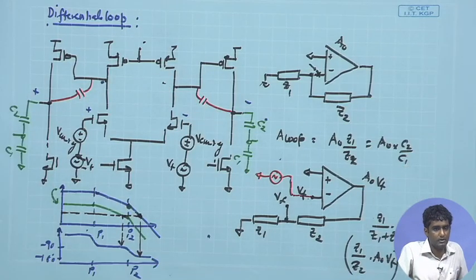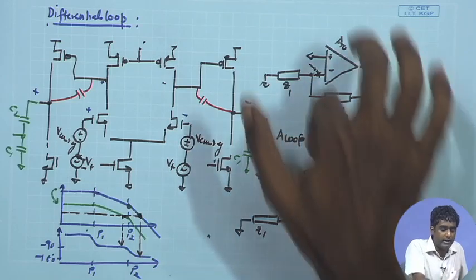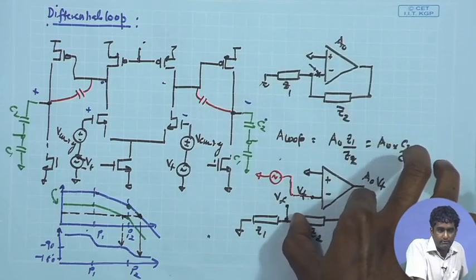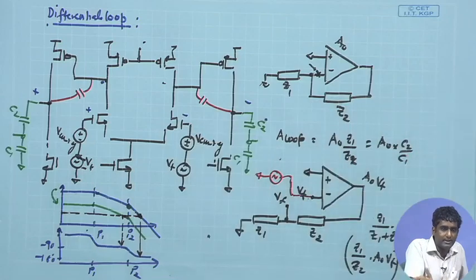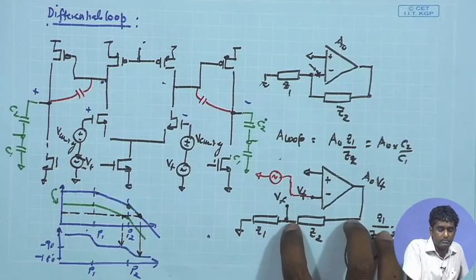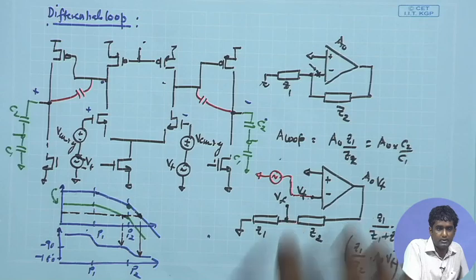How will RF affect the low frequency region, like you told now, it will give a high pass filter? So, we have discussed, right. While determining the value required for RF, we looked at the high pass response because of RF and the C2 that you have, and that must be able to pass the desired signal, and that only gave us the value of RF, because this RF produces a high pass response. That is what we had looked at.